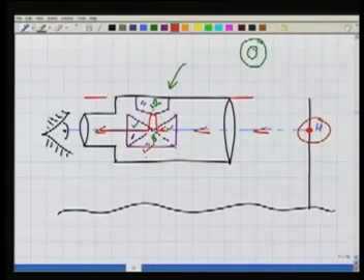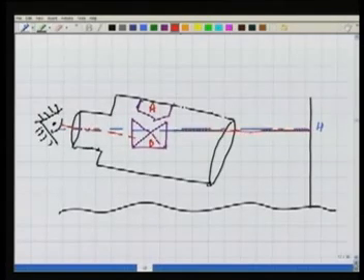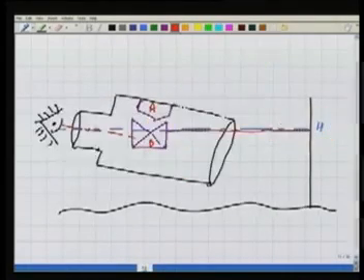But what happens if I tilt my level now? If I tilt my level, as in this case, this part A will tilt with the body of the telescope, while the B will remain where it was. Again, from the same point, because this is the horizontal line as in the previous case, if my instrument is kept here, I should read point H for the horizontal line.